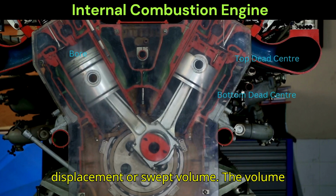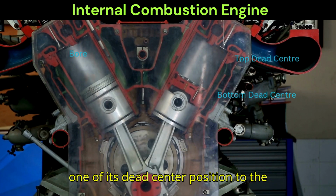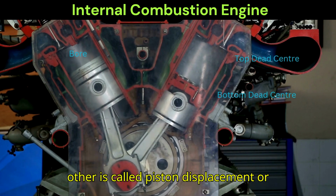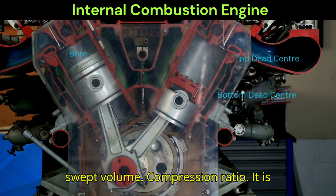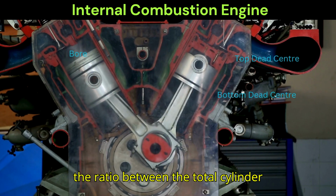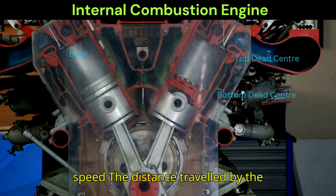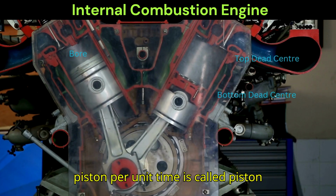Piston displacement or swept volume. The volume swept by the piston when it moves from one of its dead center positions to the other is called piston displacement or swept volume. Compression ratio. It is the ratio between the total cylinder volume and the clearance volume. Piston speed. The distance traveled by the piston per unit time is called piston speed.